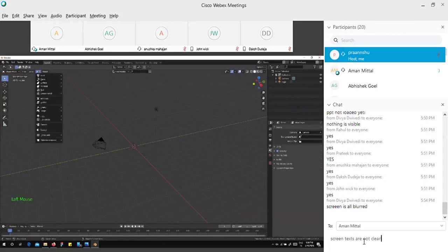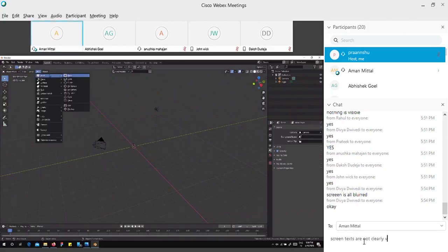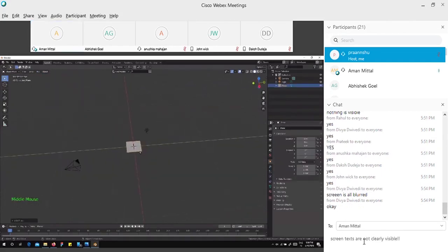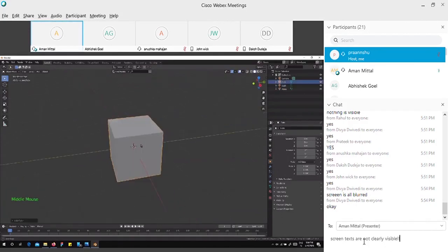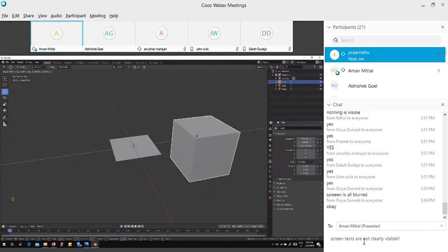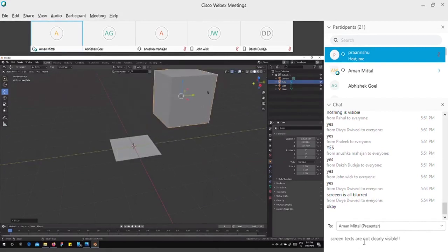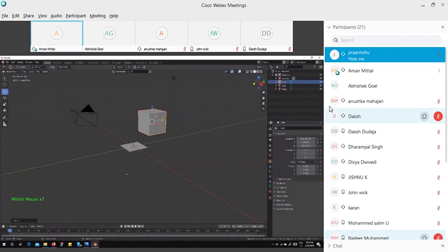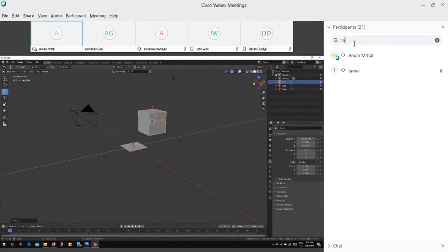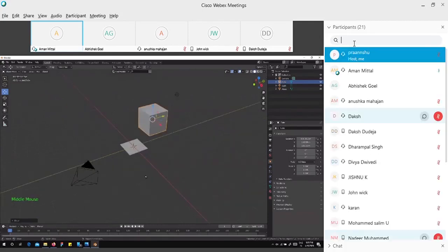So you can add different types of objects here, like a mesh object, a normal plane. The shortcut for that is just Shift A, and you will have the menu here. Plane, a cube. You can move a particular object by selecting this icon from here, or just by pressing G. So you can move the object around. If you have played any game, it is similar to that, moving around here. Okay, actually not like in a game.